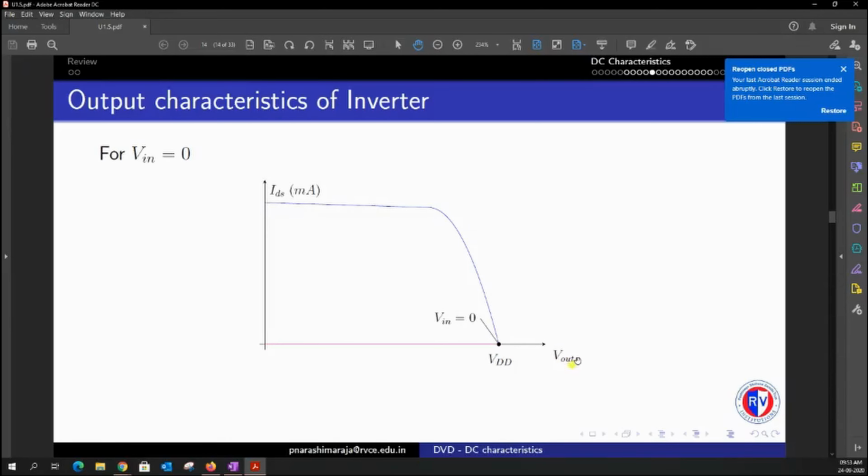And we know that this Vout is nothing but the VDS of the NMOS device, so that is equal to our VDD. Or Vout can be rewritten in terms of VDSP, something which we have discussed. Clear? So even based on that, we end up having this as our intersection point. This is the intersection point that we have for the Vout. I hope that this particular graphic is clear. And now what we do is we will try to increment the input voltage at every step and see what happens after this.